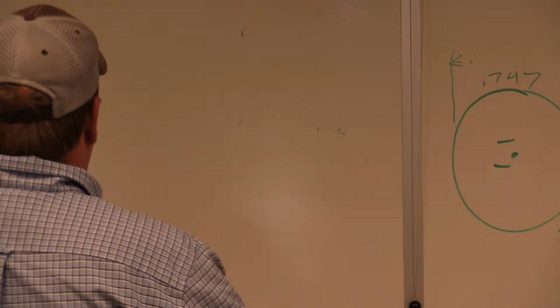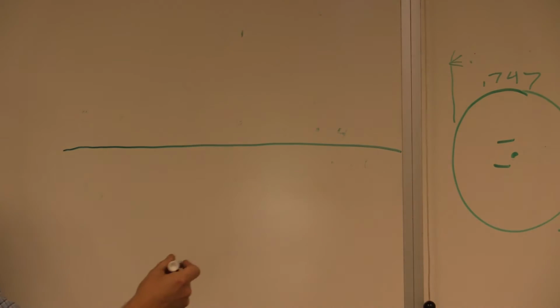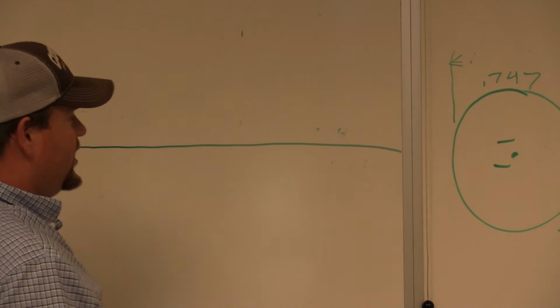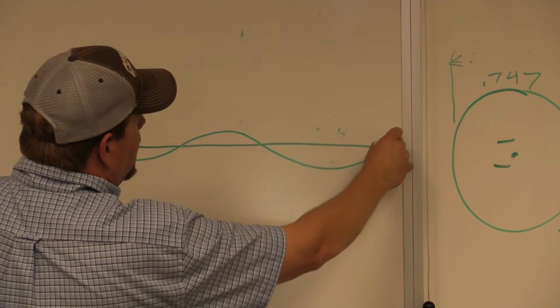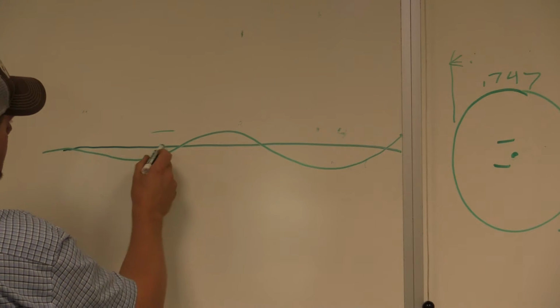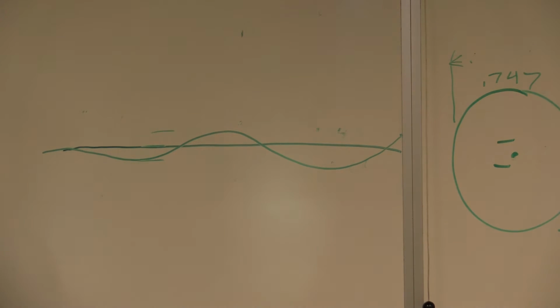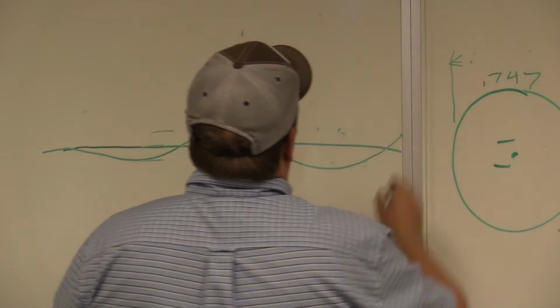That means that as we come along a straight line, pretend it's straight, I'm going to make it very drastic, it cannot vary more than 5 thousandths difference. It has to be within 5 thousandths of an inch flat, all right, on that top surface.